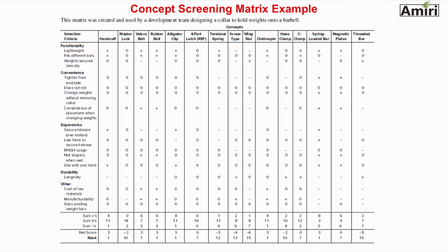These are from your textbook, the Product Design and Development textbook by McGraw-Hill, by Ulrich, that give you some idea about some of the criteria. This one is a screening matrix, so you can see they're all pluses, minuses, and zeros, and this one has a clear reference. The quick way to find it is that it's all zeros top to bottom, and every concept was compared to this one. Again, it's important to go row by row when you're doing your concept selection, one row at a time, and then you can see how they summed it up.